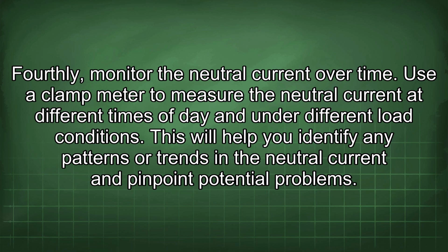Fourthly, monitor the neutral current over time. Use a clamp meter to measure the neutral current at different times of day and under different load conditions. This will help you identify any patterns or trends in the neutral current and pinpoint potential problems.